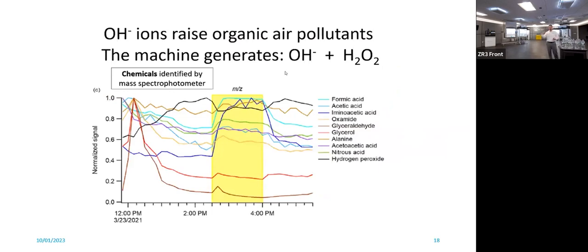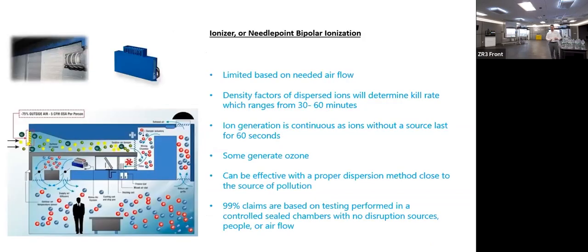So when we're releasing our own organic matter, you turn those ions on, we actually see a spike in risks associated with these types of pollutants. So again, caution yourself. Now, they do say 99%, I'll take a step back, they do say 99% effective, but understand testing was performed in a 10-inch by 10-inch cube chamber. Doesn't provide you with real-time results, real-world condition in a very dynamic setting. Anything can pass in a 10 by 10 inch chamber or even a 10 foot by 10 foot booth.